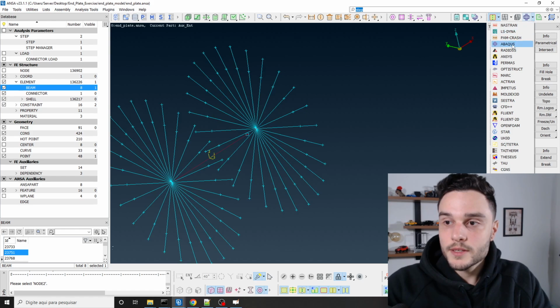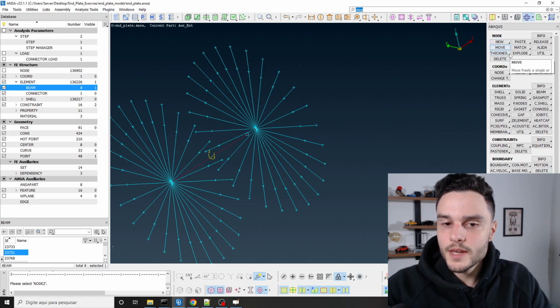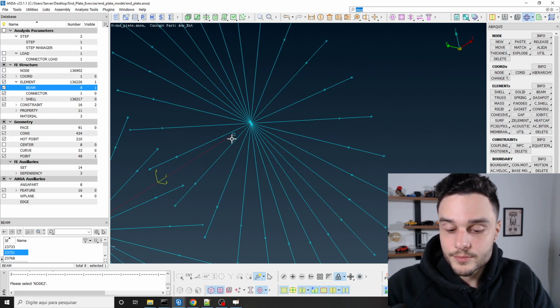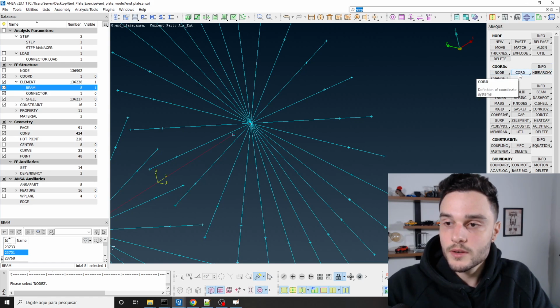Let's go to Abaqus deck. And we know that we need to have this coordinate system from here to here, right? So let's create it before we create the connector. We can do this. We have the coordinates group. There is this item here, coordinate.